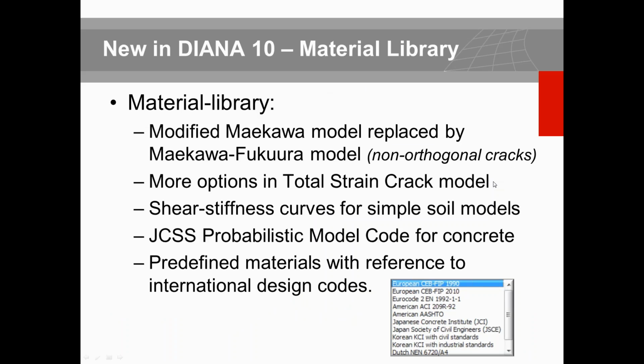Then at the material level, we have done significant work to enhance the behavior of the modified Maekawa model. We have implemented and replaced it with the new concept introduced by Professor Maekawa and his colleague, Dr. Fukuura, for definition of non-orthogonal cracks for concrete models, which are energy-dependent behavior.